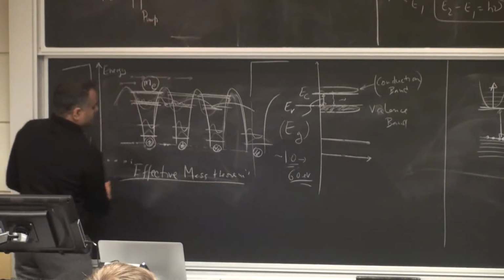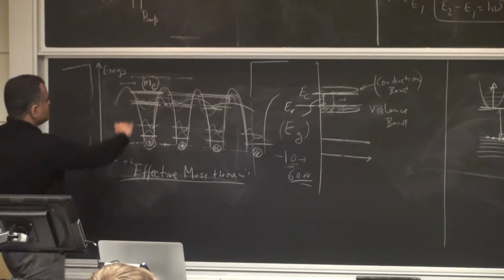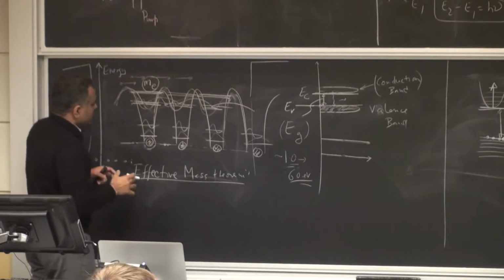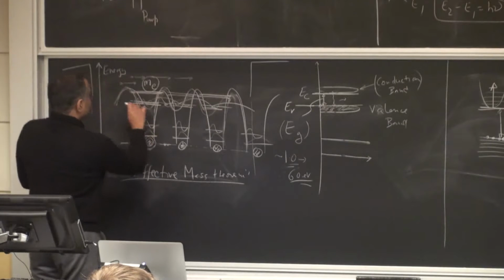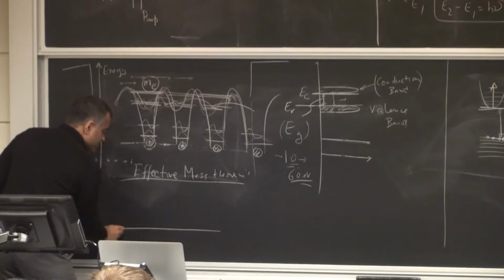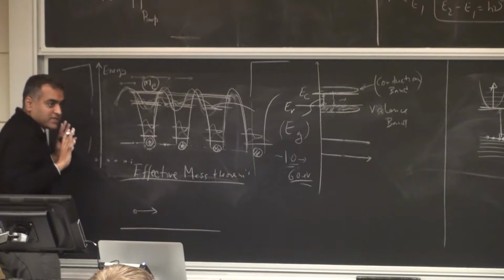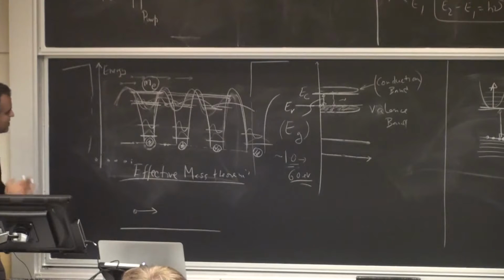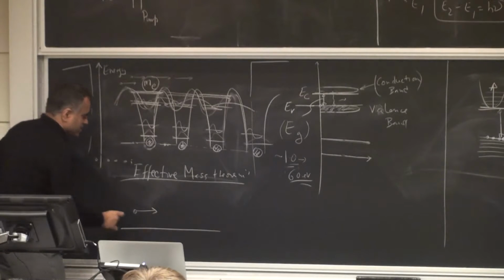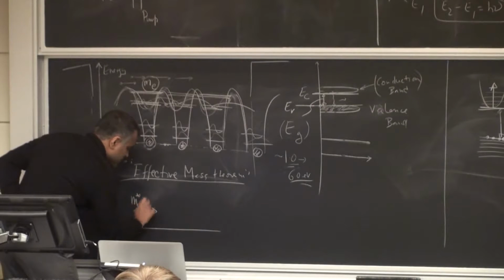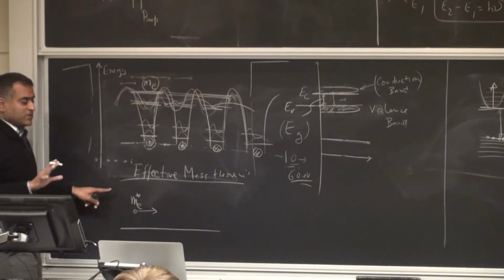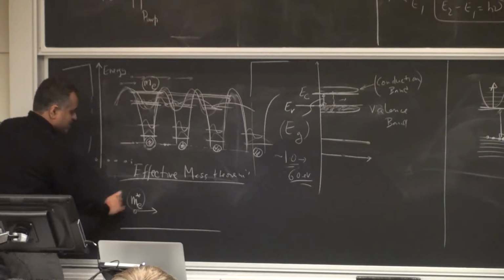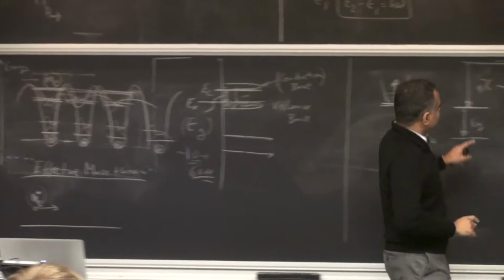And just a statement, obviously I'm not trying to derive it at all. All the details of the periodic potentials that the electron might see as it goes through a crystal can be completely absorbed by saying that instead of a periodic potential, I'm going to have a fixed potential, but the mass has changed now. It's renormalized. Mass is different. And all the information of periodicity, what atoms there are, whether it's gallium arsenide, gallium nitride, indium arsenide, whichever semiconductor you take, is buried inside this mass of the electron. So that whole sort of quantum and solid-state physics gets absorbed into this quantity, and you start kind of designing it like a classical system now.